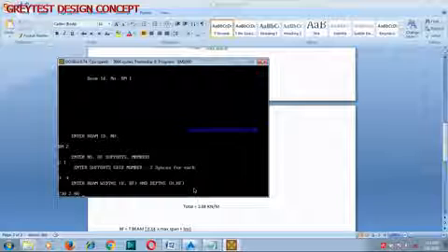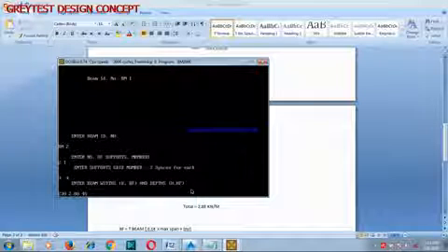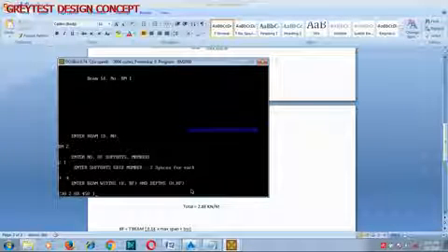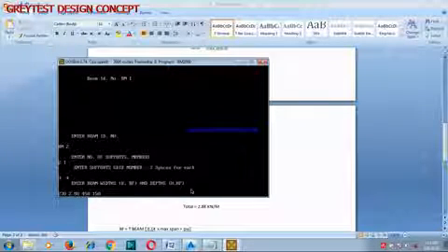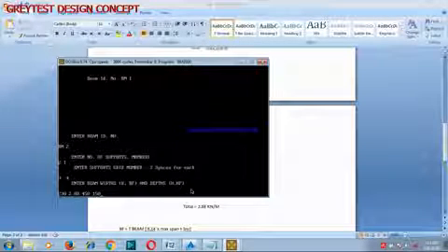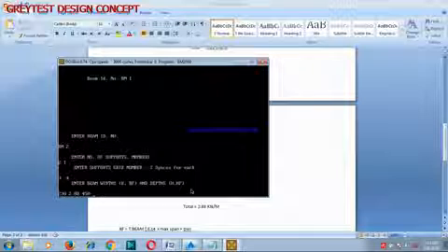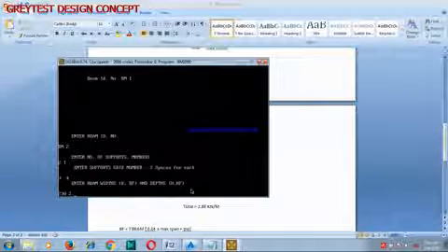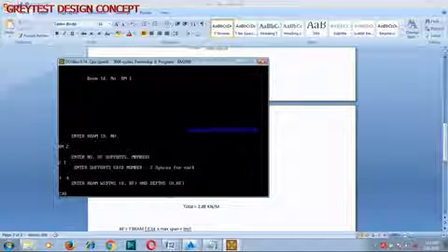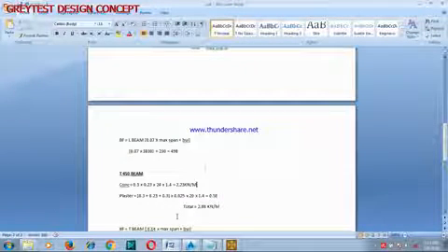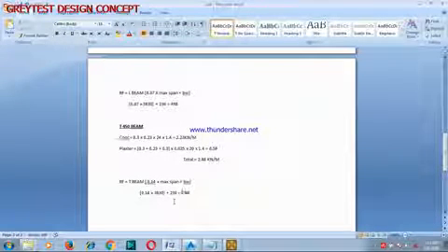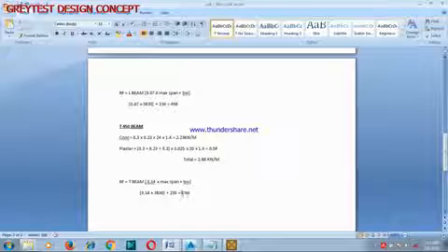Now what is the depth, which is 450? What is the height of flange? Which is 150. That's the thickness of your slab. So you must be very careful. Sorry, this value is not 2.88. I picked the wrong value. Sorry, this is what I'm supposed to use. BF, breadth of flange, 766.